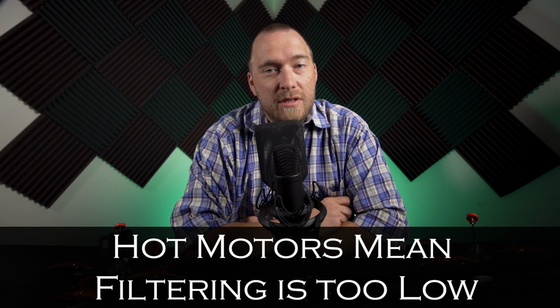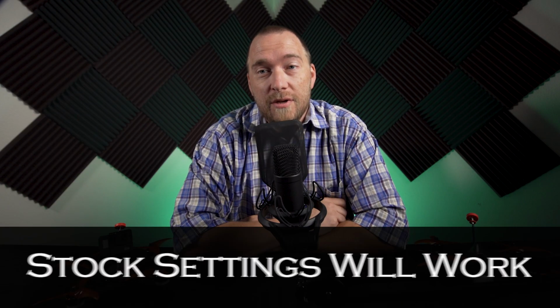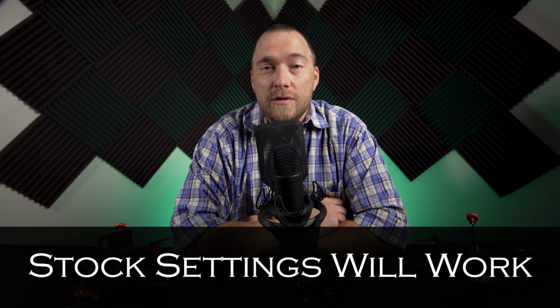Now don't let this scare you. Normally, hot motor temps will be the first indication that your filtering is getting too low. Just be careful and adjust in small steps until you find the right balance between drone performance and motor temps. Remember, it's not required to adjust your filtering. It's okay to fly with stock settings. But for those that want to get a little bit better performance out of their drone to improve their flying experience, it's worth the effort.